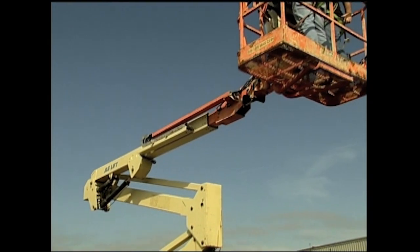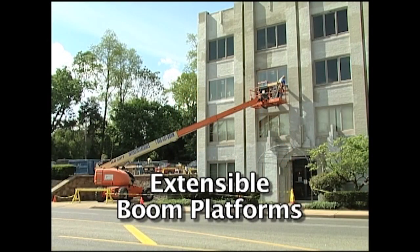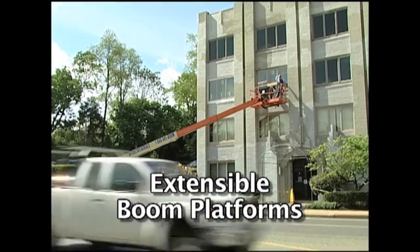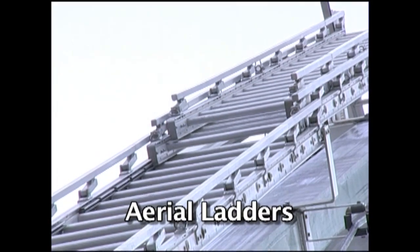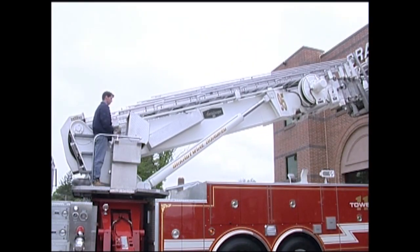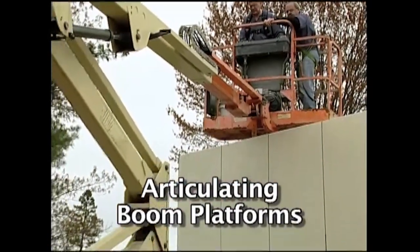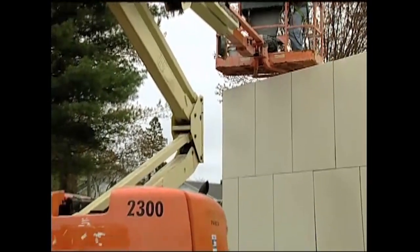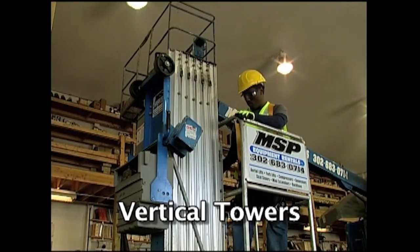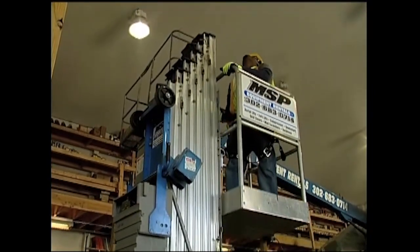Depending on the work that you're doing, there are a variety of aerial lifts to choose from. Extensible boom platforms use a single arm to lift their work platform to the desired height. Aerial ladders consist of a single or multiple section extendable ladder, such as the powered ladders on fire trucks. Articulating boom platforms contain two or more hinged boom sections, which allow the arm to maneuver into difficult-to-reach places. Vertical towers are designed to elevate a platform straight into the air, using a mechanism such as a telescoping mast.